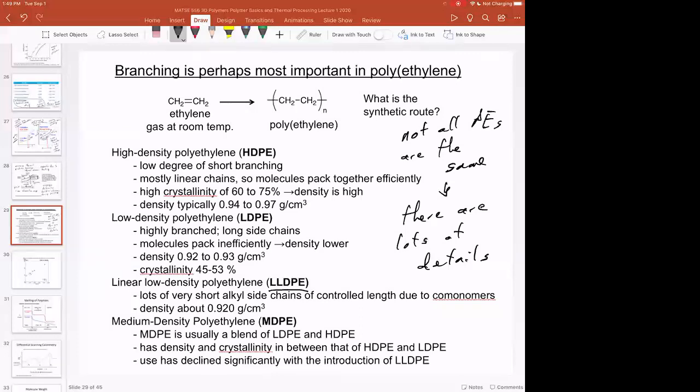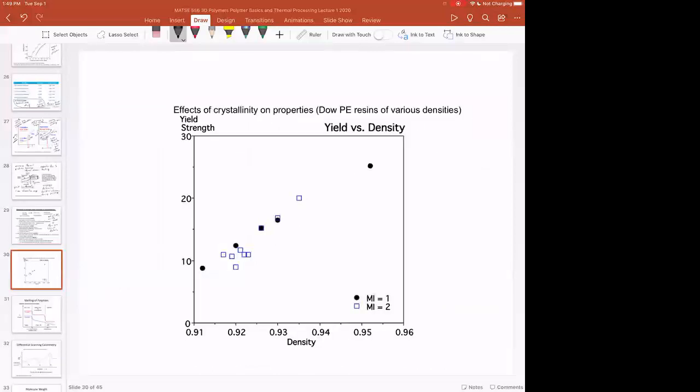how the nomenclature of the polymer or how the authors are describing the polymer relates to the polymer properties and the polymer industry, because all these polymers are generally made in big chemical plants. They're made for injection molding, and we just siphon off a little bit of this feedstock for additive manufacturing. The reason why we have lots of different grades of polymers is that we can span lots of different properties of polymers. So this is just one